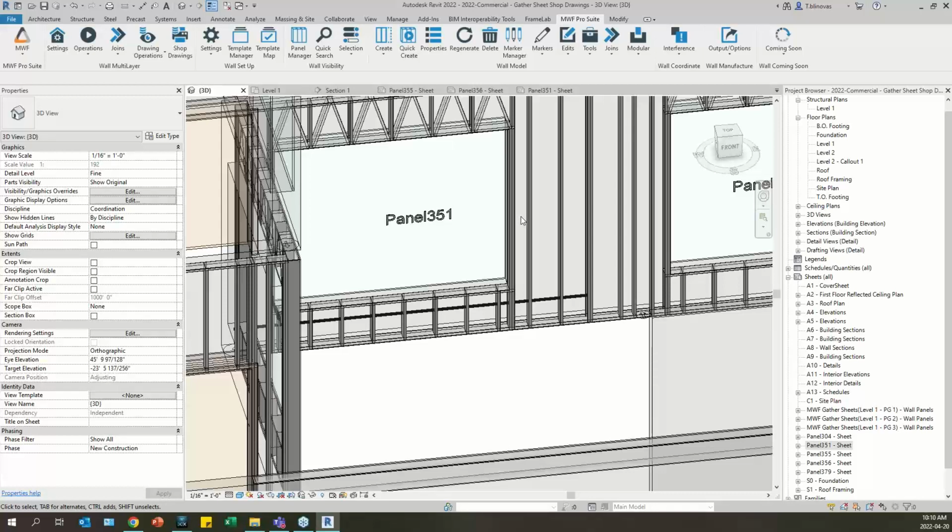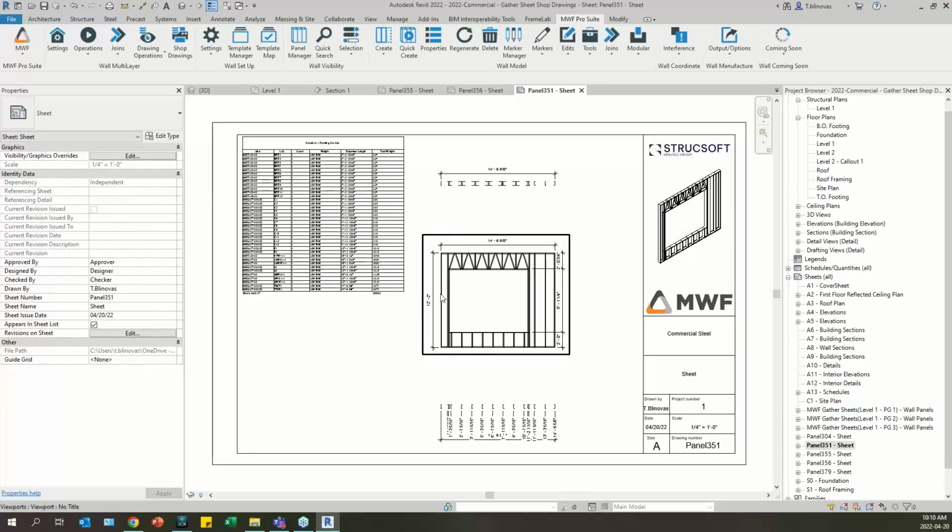One option is, if you do want to see it, you could change it in the settings of your elevation view. We have that option to show the visible categories. You can just check off the categories that you do want to see. But if it's something specific or just one element, what you could do is use the override hidden.